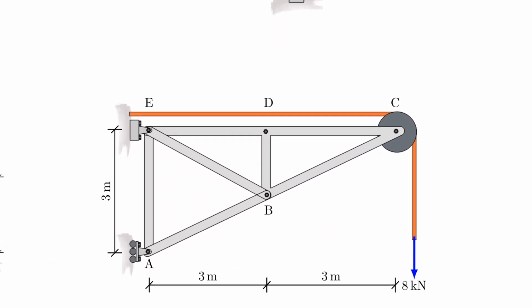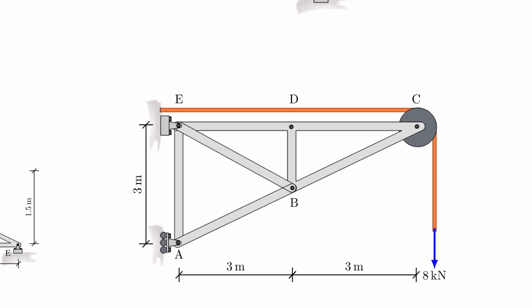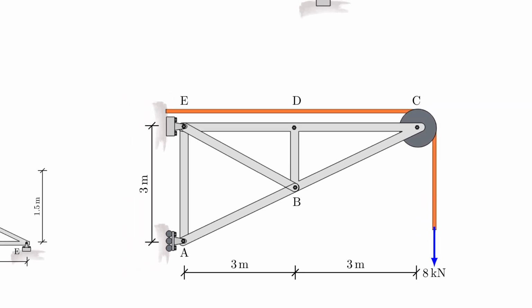Last but not least, here we have the node D, and node D again has this condition where this has to go to 0. And now node B has the same condition, so that has to go to 0. And therefore the real structure that participates in the load carrying mechanism does look like this. And that concludes our zero force members.